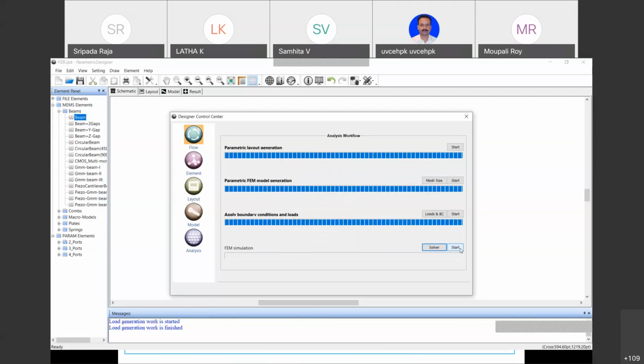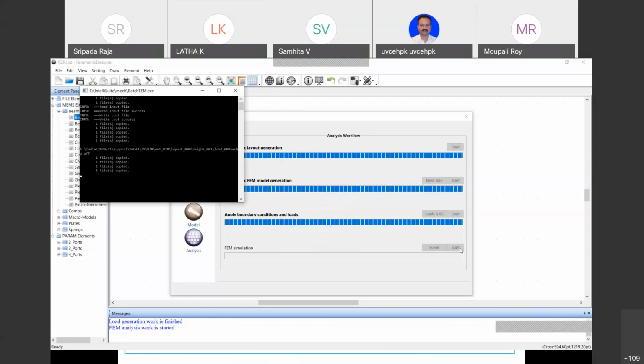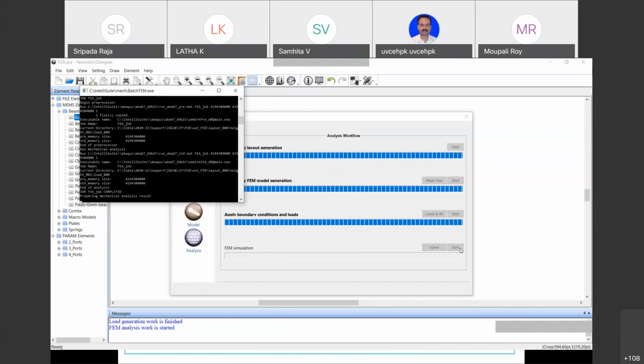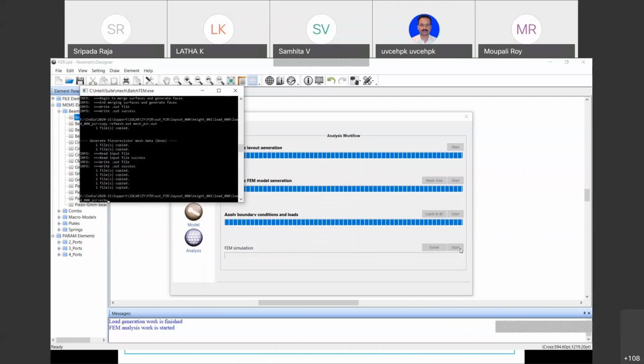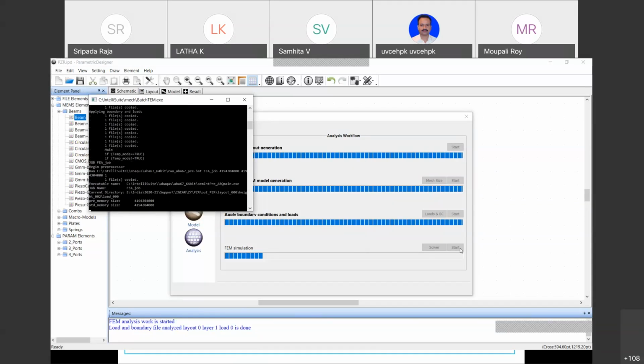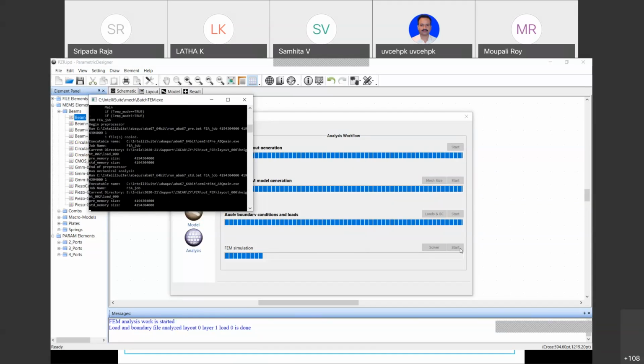and click start. So now when I click start, for 6 variants of thickness, the software will simulate 0.1 kilopascal. 1 E minus 3 megapascal is what the unit input that is given. So it is 1 kilopascal. So 1 kilopascal of pressure is applied on the device whose thickness keeps changing 6 times between 19.5 to 20.5.